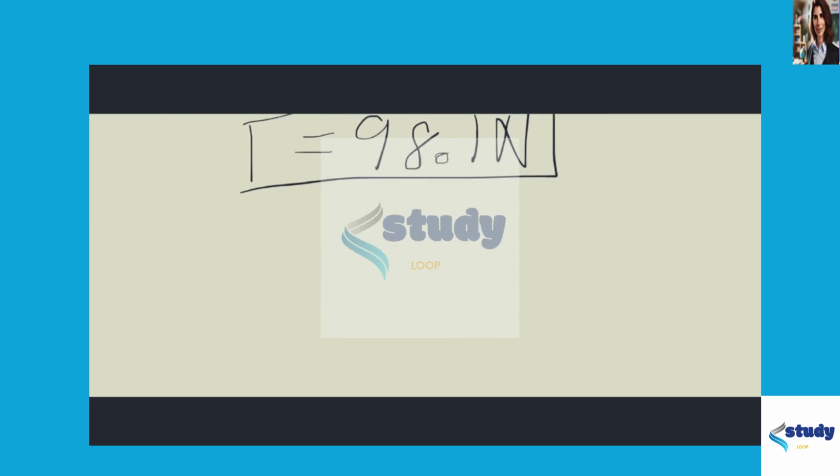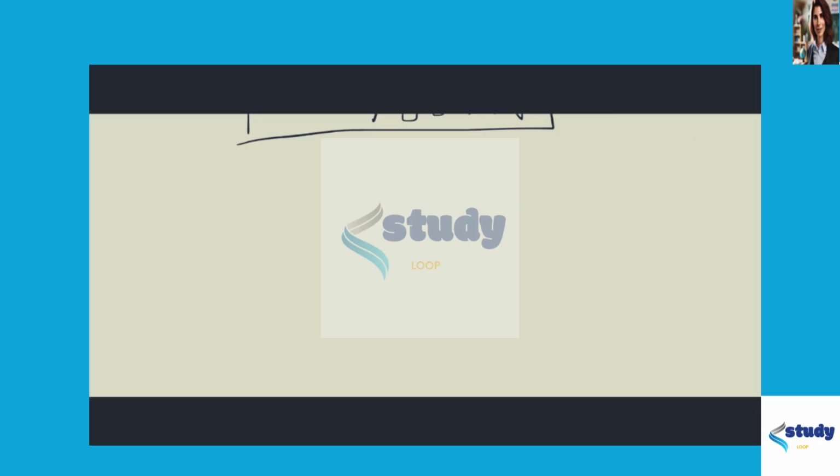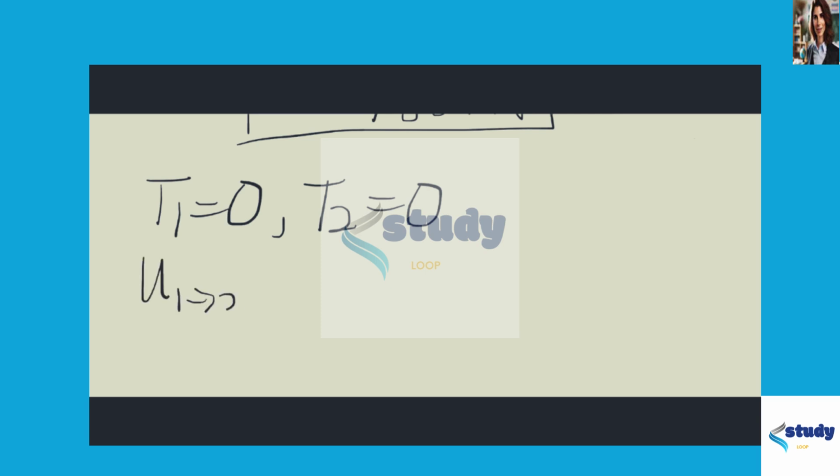Now we're going to move over to the nonlinear spring. So again, the same argument holds. The kinetic energy in the beginning is 0. Kinetic energy at the end is 0 because x max also occurs when the kinetic energy is equivalent to 0. So now we can write out the expression for the work done by the spring force and the weight force. So now we're going to have an integral because this is a nonlinear spring. So we have to integrate to solve for the work done by that spring force.